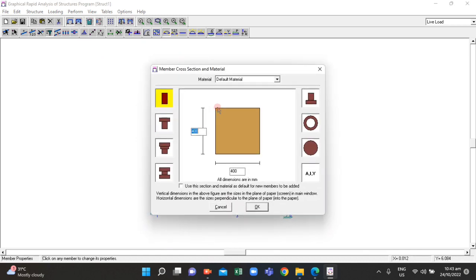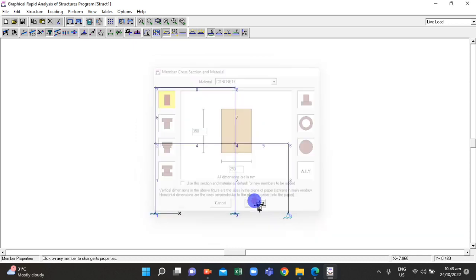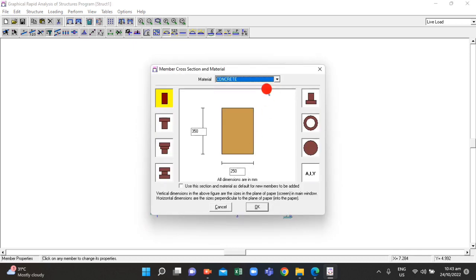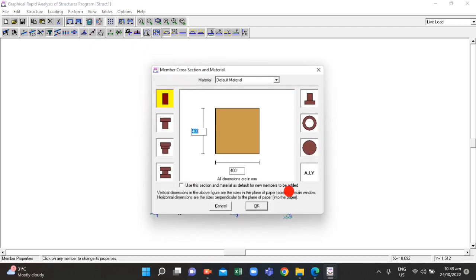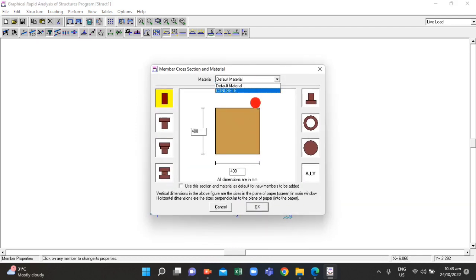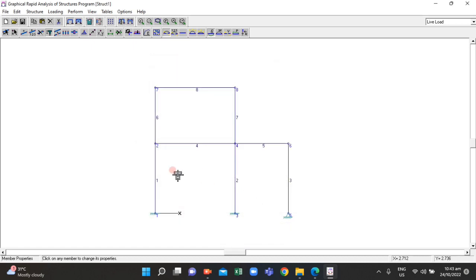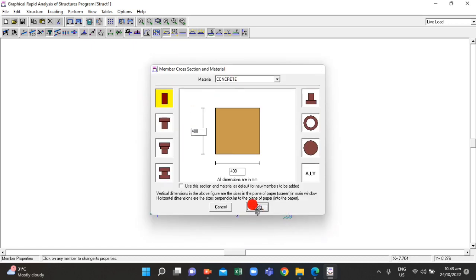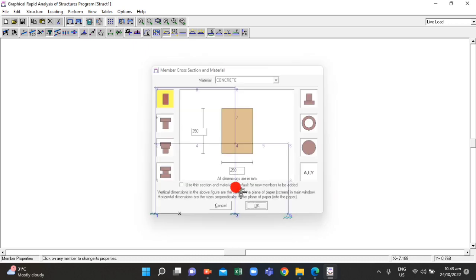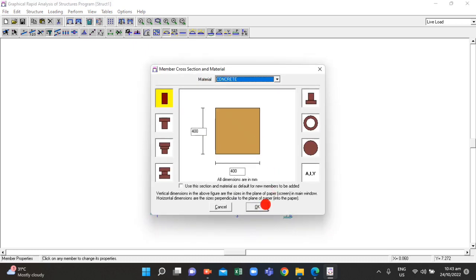It can be highlighted to apply uniform concrete, and set the material to concrete. Because basically it will really give a big impact, a big difference. The material properties used in different structures will make the analysis results really different. So let's make sure that the materials used in our structure, particularly in the analysis, are correct. It's exactly what is given. So that's it.